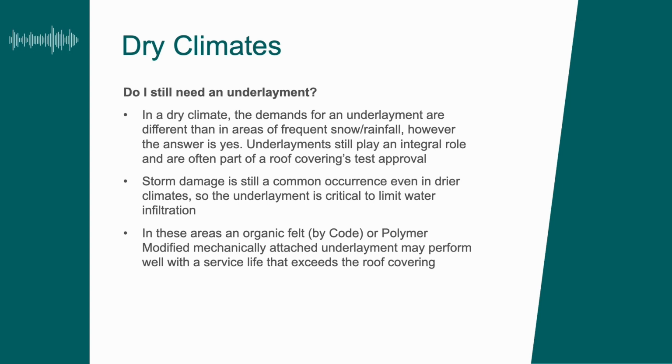Example, things like VersaShield, for example, that some of those are in product approvals for other roof covering products that require it as a fire barrier. There are other companies that are making underlayments that have some fireproofing characteristics that will help. And they've been tested with various things, so it's something to look at and keep in mind when you're using certain roof coverings.